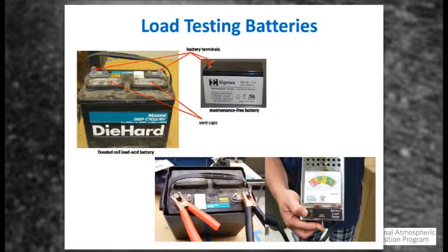Anything you want to add? No, just make sure that, as you were talking about batteries going bad, if one's going bad, then the other two probably aren't far behind. Most sites will get into a maintenance schedule where, instead of trying to determine which one is bad, they replace two of them, or all three of them, whatever you have in your bank of batteries, on an annual basis, just to alleviate the problems. And that's if it's within your budget.